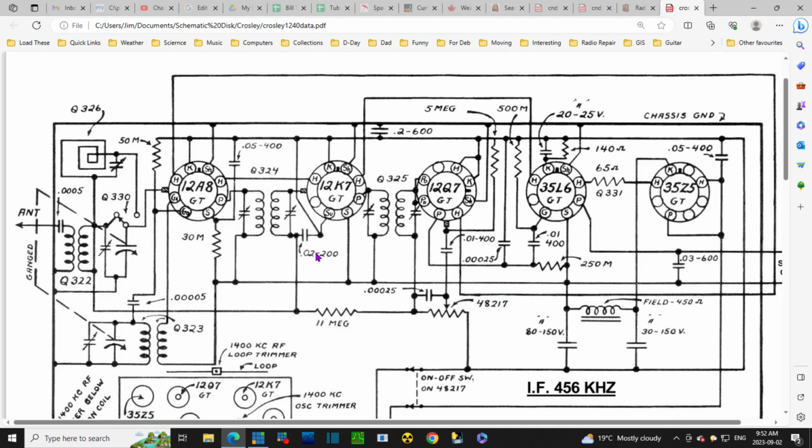So what happens if this capacitor is not so good? If it has no capacity, then you would get variations in the voltage on this side that would follow very precisely the variations over here. You're dealing with the grids over here and the output from those tubes. You have basically an oscillator feedback system set up. So I think without this capacitor, you might get some weird feedback things going on.